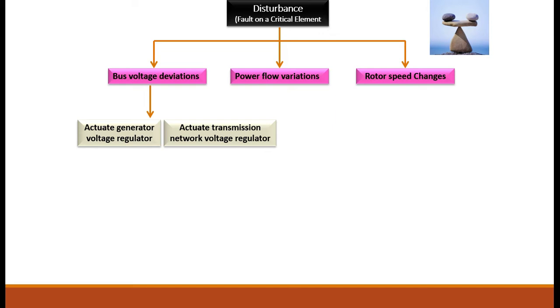The output voltage of the generator changes only when the voltage regulator instructs the excitation system to do so, irrespective of the speed response of the exciter. That is, the regulator sends the changes in the output voltage and causes corrective action to take place, so that once again a steady voltage is achieved at the different parts of the circuit.